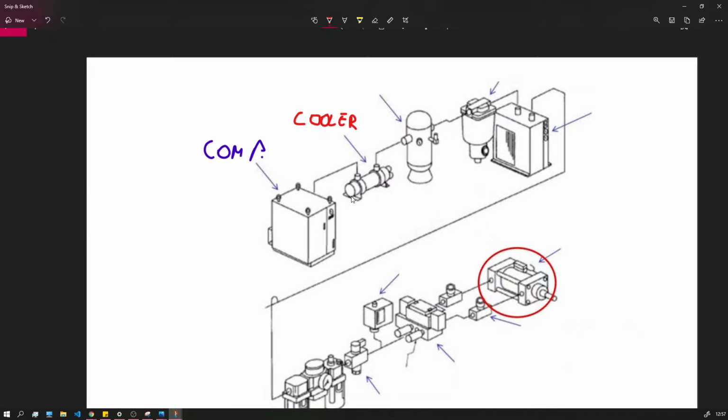But yeah, when we compress air, dew point is really important. If we are close to the dew point with the air that we are sucking into the compressor, then it's really easy to bring in some water. And usually the water starts to condense out of the air that we're compressing by cooling the air.